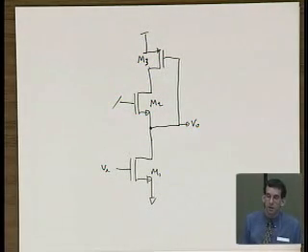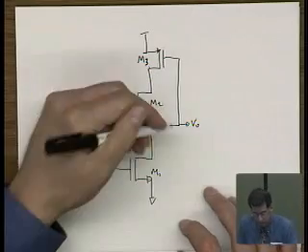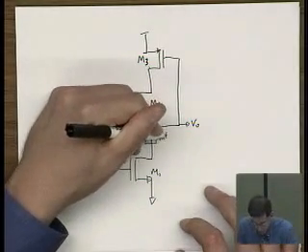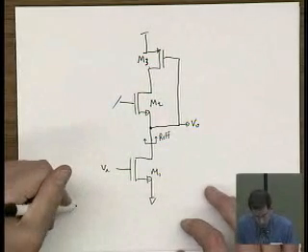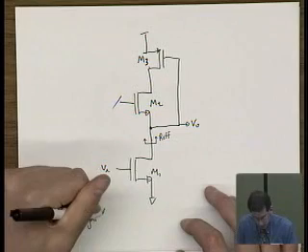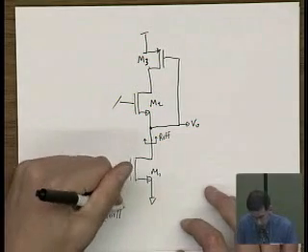That's true. Spice will certainly give you a number, but the number won't help. So with this, what I would do is, again, R effective looking up, and then we know that the gain is equal to gm1 times ro1 parallel R effective.